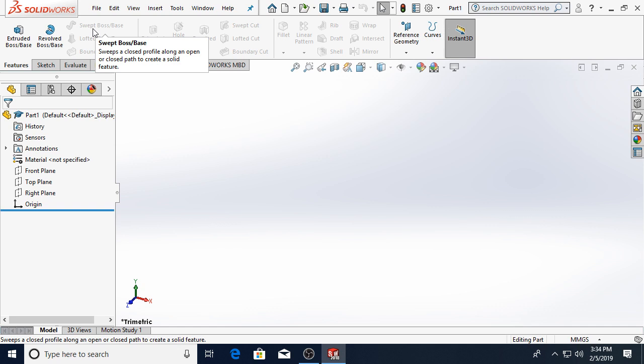We can create one sketch that represents the shape to sweep through space. In this case, that would be a circle. And then we create another sketch that represents the path to follow that sketch with. So one of our sketches will be a circle. The other sketch will be like a skeleton of this handle. It'll be a line, it'll be an arc, it'll be a line, an arc, and a line. Does that make sense?